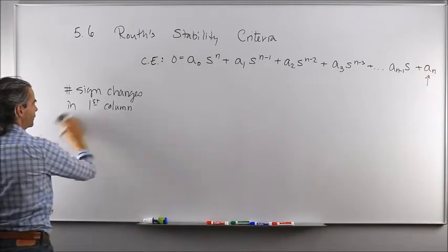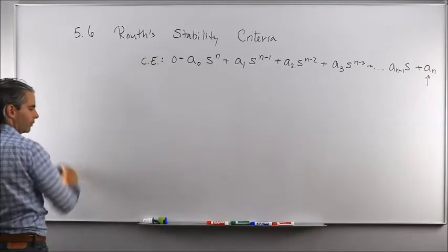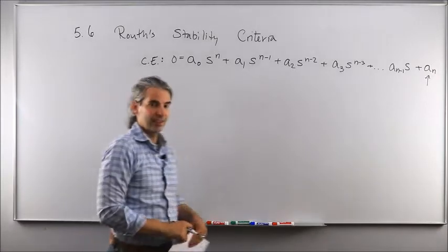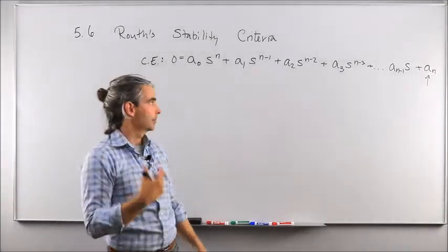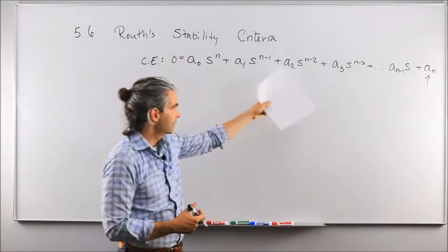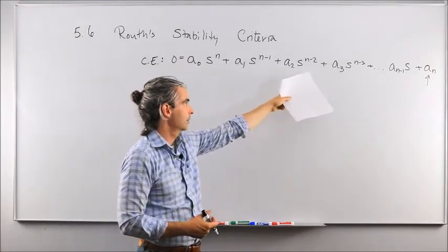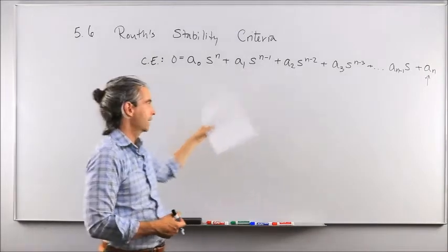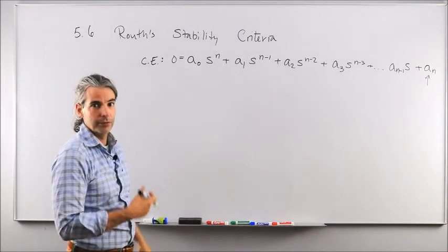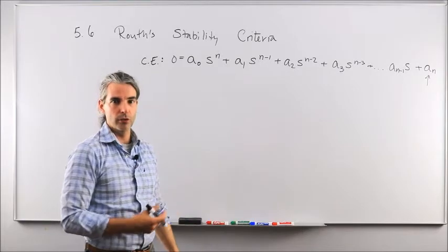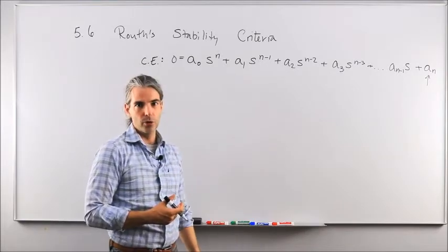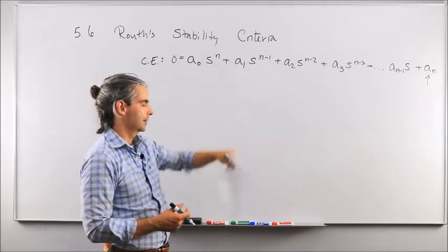And that's the beauty of it, because you don't need to solve for the poles to know exactly where they are, because if all you need to know is whether or not this is related to an asymptotically stable, a stable, or an unstable closed-loop transfer function, well, that Routh criterion will give you the answer right away without having the necessity to solve for all the individual poles related to that characteristic equation.